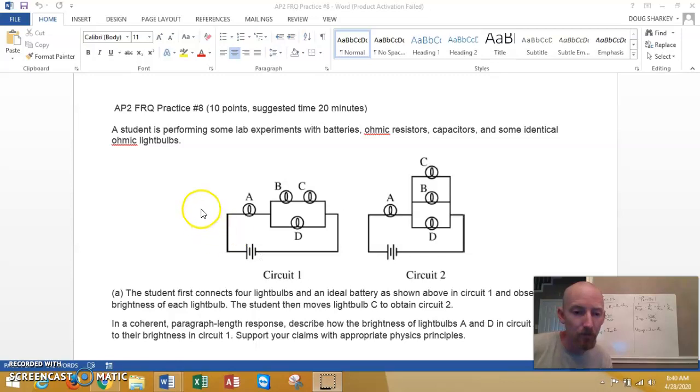And so when we work problems, the first thing is to resolve these circuits. We have to figure out each little piece. It's sort of like a puzzle. We have to say, well, these are in series, so we'll add them up, and then those two would be in parallel, so we'll add them up, and then you have A, and all of these are really just in series, and we add them up, and we can figure out total current and things like this.